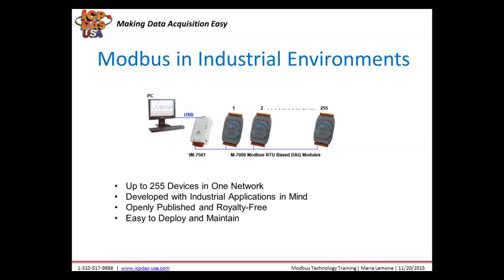Modbus applications are easy to deploy and maintain. Each Modbus device in a network is given a unique address. In serial Modbus RTU networks, only the node assigned as the master may initiate commands. In Ethernet-based Modbus TCP networks, any device can send out a Modbus command. One master device is usually configured to send the Modbus commands. A Modbus command contains the unique Modbus address of the destination device. Only the destination device will act on the command, even though other devices might receive it. It's kind of like broadcast communication in UDP.